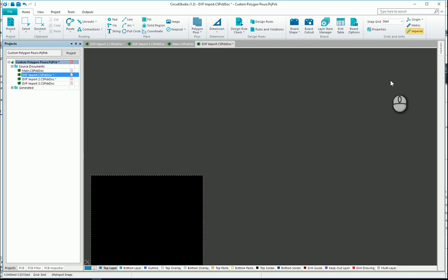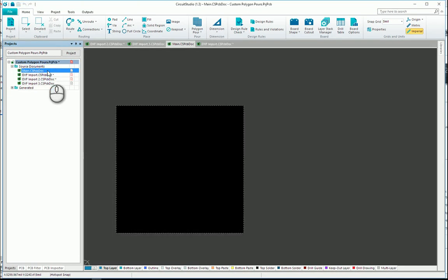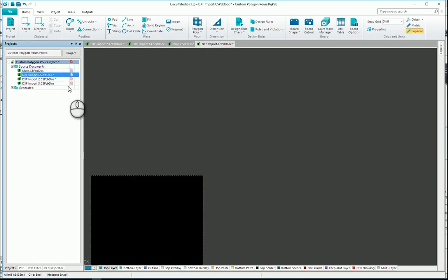And in my case, there were very subtle changes. So what I came up with and use is I have my main PCB document here. And this is where all your nets are connected and your components are added and moved around. And then for every DXF import, whether it's a group of imports or a single import, I create a different PCB doc that's added to the project.